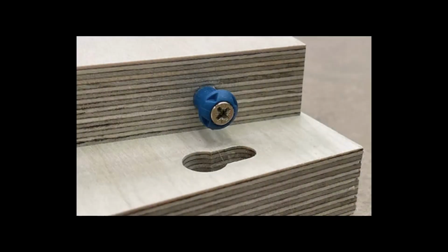Peanut 2 and Peanut 3 require 2 types of processing: the routed slot on a panel face and the 6mm hole in the edge of the mating part. If the nested CNC does not support horizontal drilling, the edge hole must be completed with a separate edge boring operation, a peanut jig, or compatible drilling and insertion equipment.